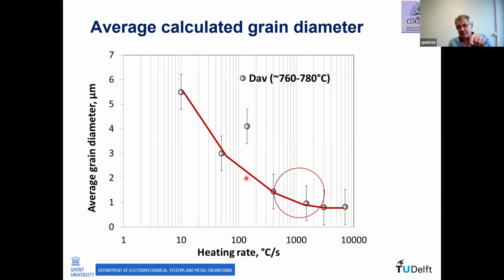We had this quench delay because our samples here were heat treated in the salt bath. So we have a robot which needs around 8 seconds to transfer the sample from one salt bath to another salt bath for quenching. That's the story. As you see, the effect can be destroyed immediately by this quench delay, which is a very important point.